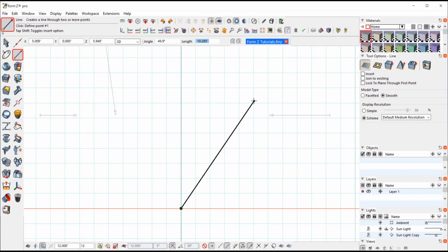And there's the line. Again, I'm going to work in just line and not in shaded. So that's locked. I have my perpendicular and horizontal locked, so it's going to go straight up. I'm just going to make this a random height. And if I just click once, it will be that length. The length number is moving. I can go in there and make that a specific length.